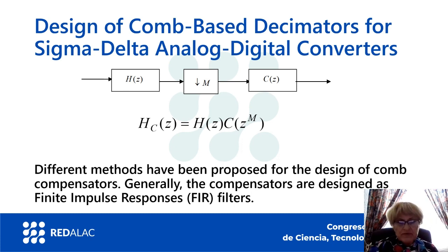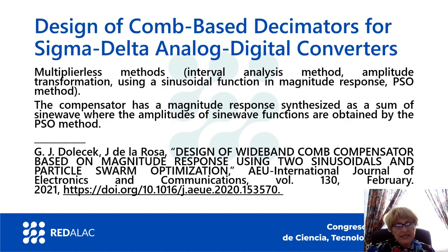Different methods have been proposed to design compensators. Generally, the compensators are designed as FIR filters to have a linear phase. Multiplierless methods like the interval analysis method, amplitude transformation, using sinusoidal function magnitude response, and particle swarm optimization are methods used for design of compensators.